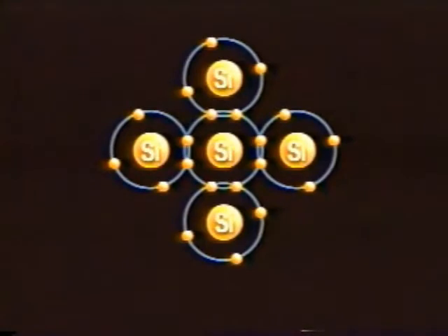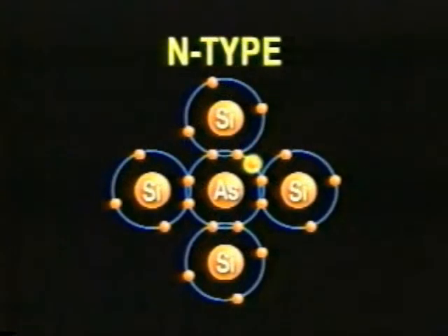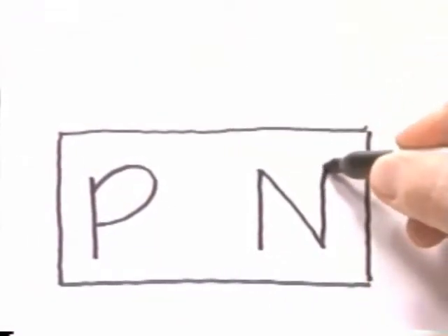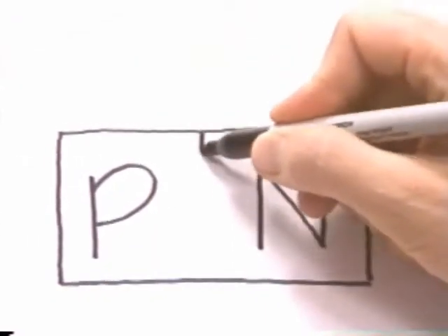You were introduced to concepts of electron flow and hole flow within the crystal. You saw how pure silicon can be doped to form either P material or N material. You also saw that a junction diode can be created by doping a silicon crystal with P material on one side and N material on the other.